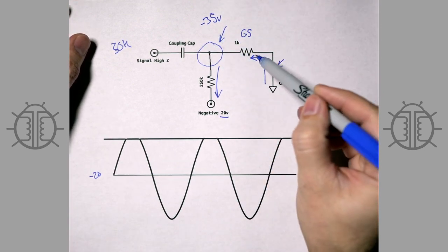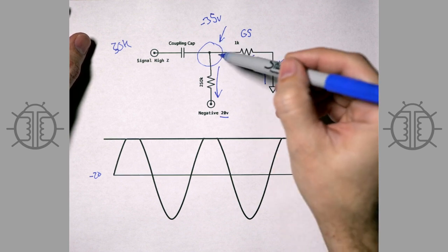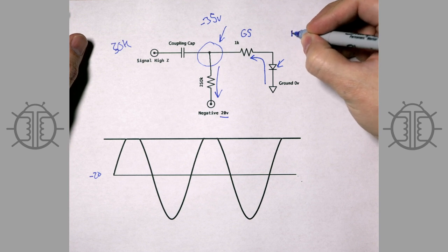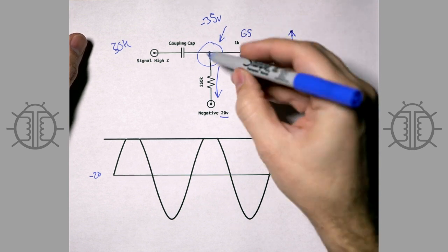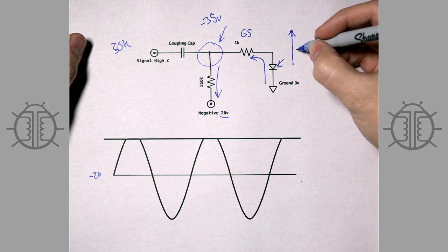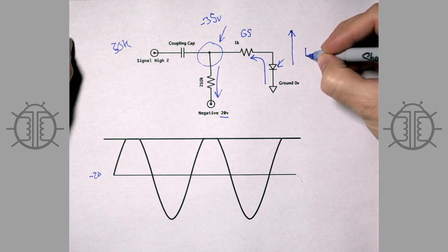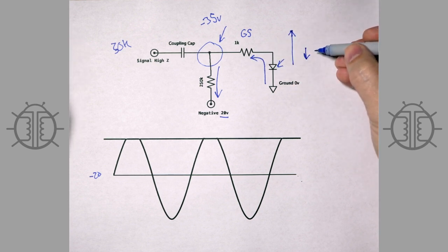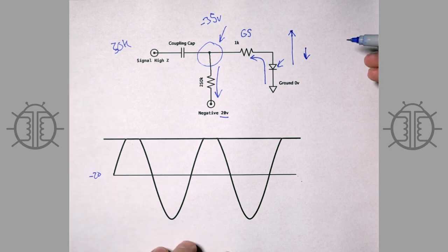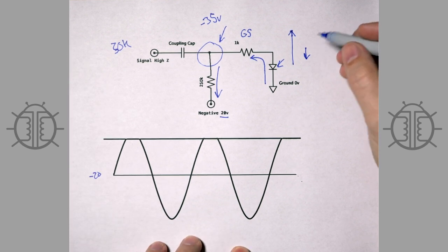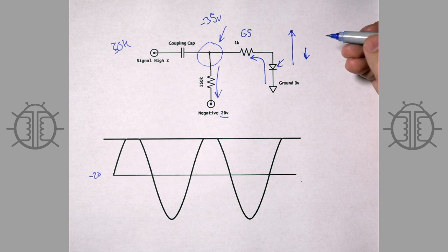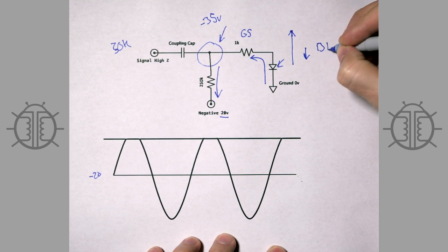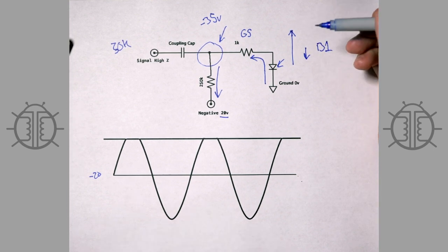And that is, like previously mentioned, this voltage here is what's controlling the bias current of the tube. And so if you make this much more negative, the bias current of the tube drops, and could even turn off, and in many cases does turn off. And so in an AB amplifier, at that point it's now a class B amplifier, a B1 amplifier, if the output tube turns off. And we'll talk about why that's bad in a minute.